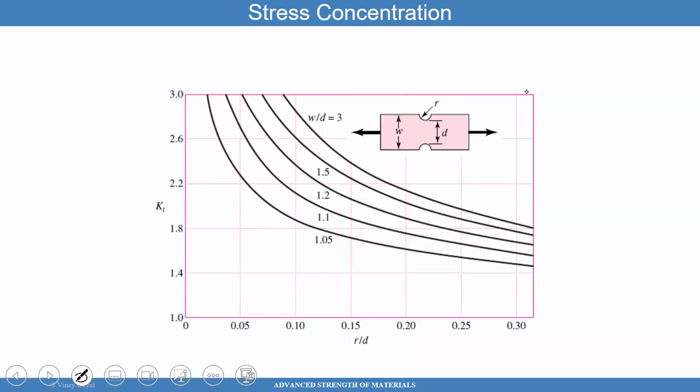So here, again, what I'll do is to look at, actually, I think in this one, again, a different problem where the load is applied far field, and you have to figure out how to use this formula. So again, very similar situation where you calculate KT. This one should be very simple to determine what sigma naught is, right? We should know what sigma naught is. Sigma naught in this case is this cross-sectional area there, the one there. I drew it slanted, but you know what I mean.